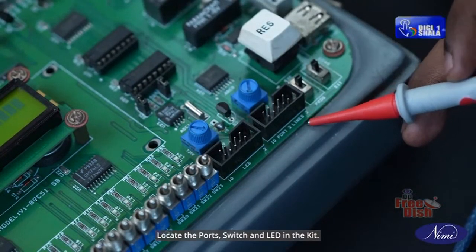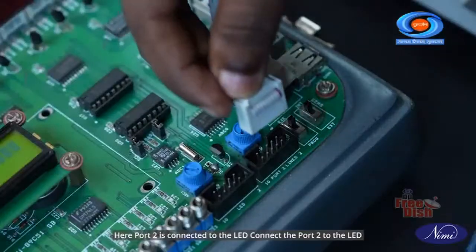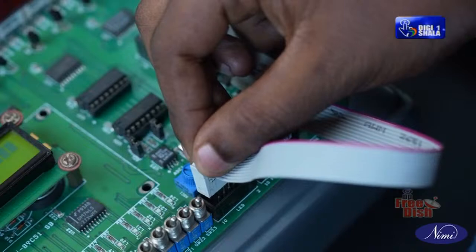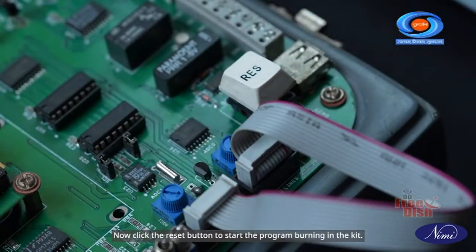Locate the ports, switch and LED in the kit. Use FRC cables, female to female, for connecting the ports. Here, port 2 is connected to the LED. Connect port 2 to the LED. Now click the Reset button to start the program burning in the kit.